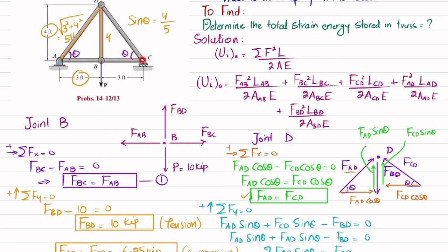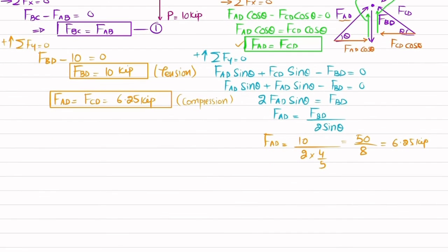So you can see here you will be having one load that will be the reaction force, which will be Cy, and this will apply load in this direction, and this member will apply load in this direction. Because you can see due to this load, this will be in tension. As a result, this will exert force at point C in this direction, and this member will exert load in this direction. Clear? So we will draw the free body diagram at joint C.